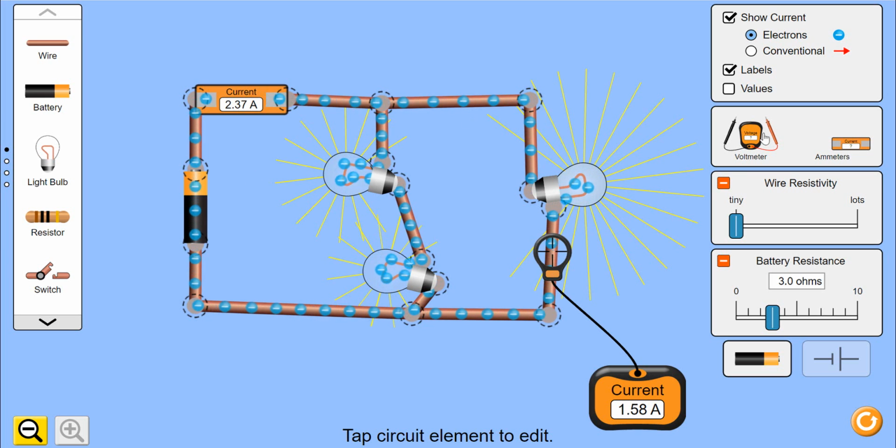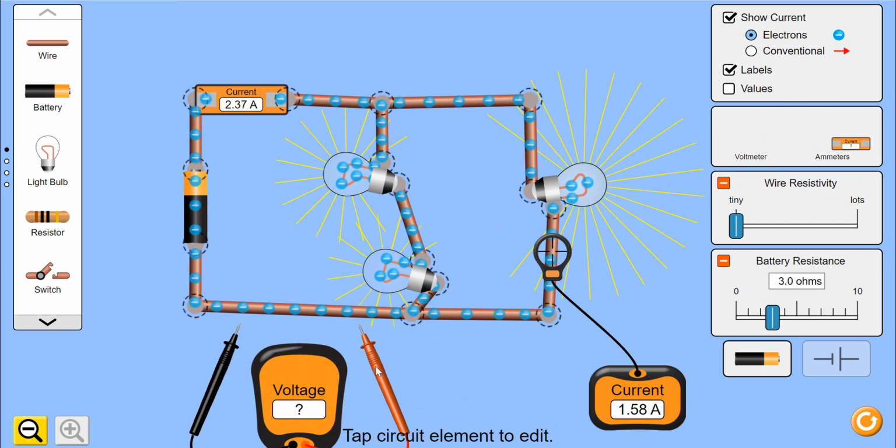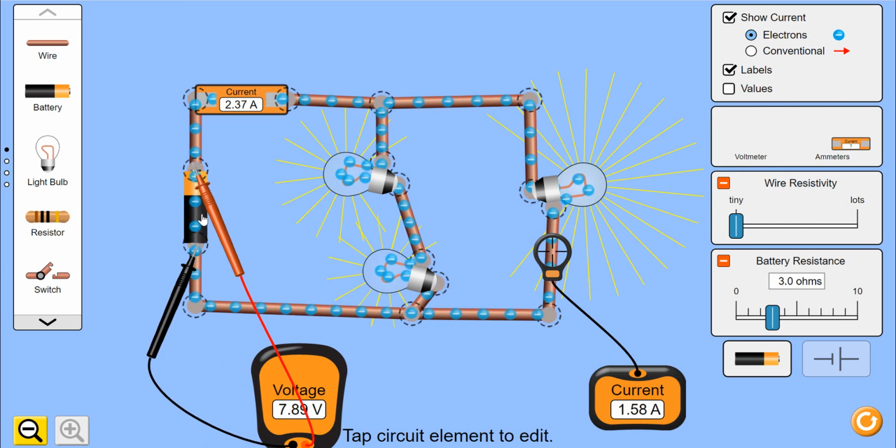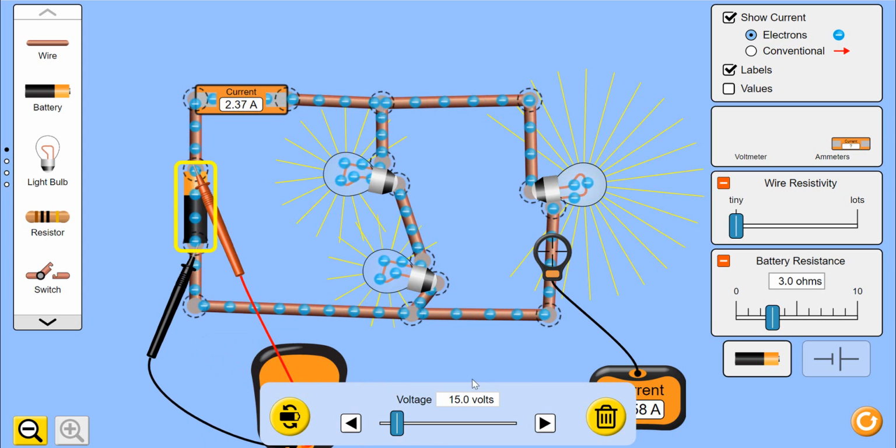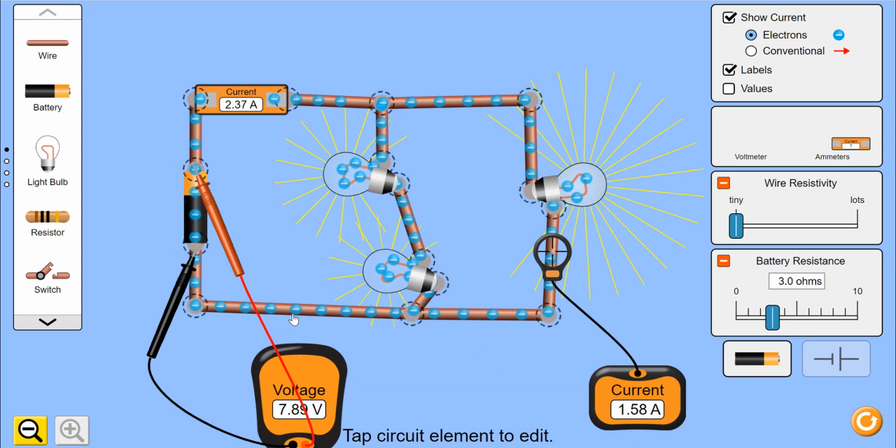I'm going to lose some of the voltage. If I pull up my voltmeter, I'm expecting this one here will be something less than the 15 it should have been. I had qualified it here to be a 15 volt battery, and yet if you look at the voltage left over, given the internal resistance, I subtract off the I times little r for internal resistance, the overall terminal voltage is actually decreased.